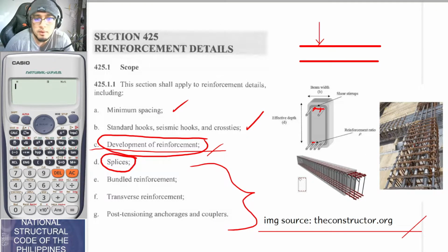If you would now be painting your rebars with epoxy as a non-corrosive measure, if corrosion is to be a main issue here, you must paint them in epoxy. However, if you paint your rebars in epoxy, they would now be slippery, as compared to if they are not coated.